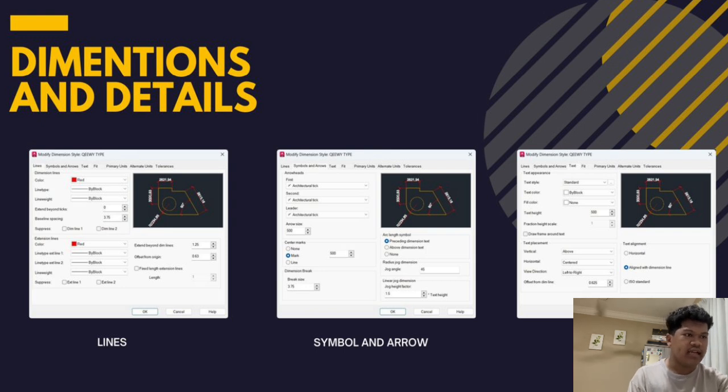For the symbol and arrow, I prefer the arrow to be big, so I chose an arrow size of 500, and I picked a mark so it is easy to see. Next, for the text, I also prefer the text to be bigger so we can easily see it. So the text height I chose is 500.